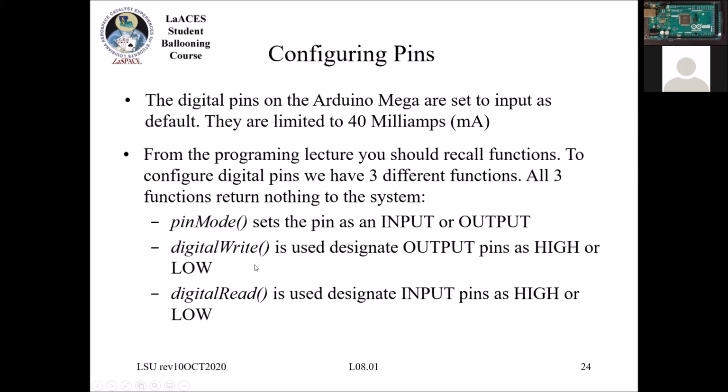The digital write command is what's used to switch an output pin to either high or low. And the digital read command pulls what is on the pin. So it checks the value of the pin. Is it high or low? And that'll return a true or a false.